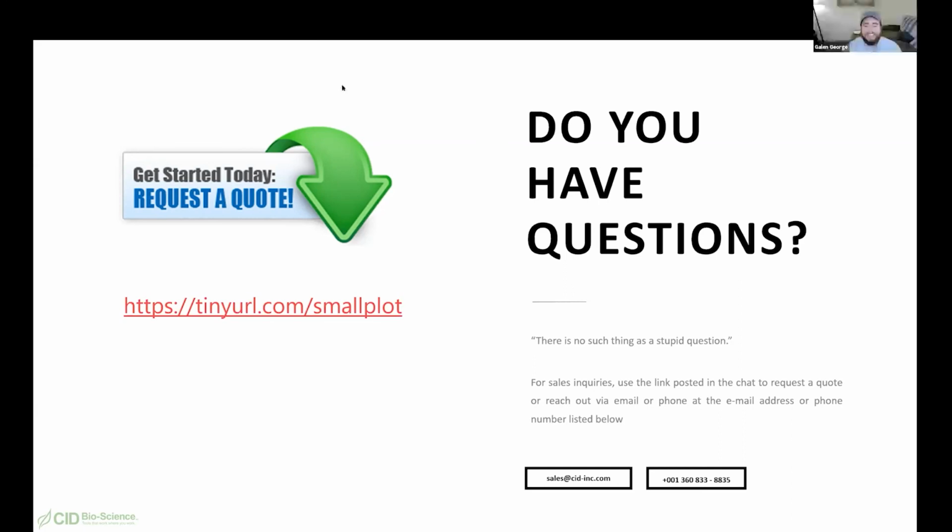So basically, Plot Phoenix does georeference the orthomosaics that it generates after stitching your images. However, the absolute accuracy of the georeferencing is only going to be as good as the GPS that's on your drone. So usually it's standard low-grade GPS that we're working with. That being said, it turns out that you do not need very good absolute accuracy of georeferencing in order to extract your plots from your imagery and do your analysis and have all of your outputs labeled by plot number. So we basically found a way to bypass the need for centimeter level accurate GPS. You really just don't need it for plot level work. Thanks, Anthony. Sure. Thank you. That was a great answer.